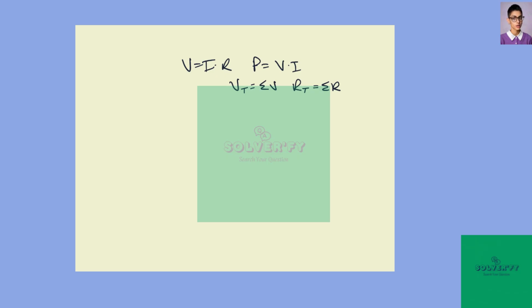So in this circuit there are two voltage sources, and the smaller one, the 6 volt, we'll just call it V sub 6. It supplies 6 volts, and the voltage from V12 is actually minus 12 volts. It goes the other direction. You can see if we're working clockwise that it is absorbing power and not providing it.